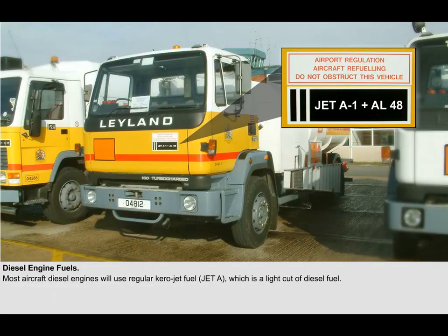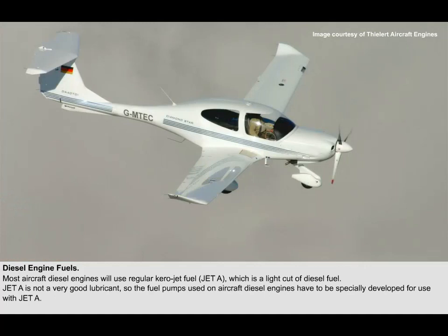Most aircraft diesel engines will use regular kerosene fuel, Jet A, which is a light cut of diesel fuel. Jet A is not a very good lubricant, a problem which has to be especially addressed in the fuel pumps used on gas turbine engines. The fuel pumps used on aircraft diesel engines are no exception. They have to be specially developed for use with Jet A.